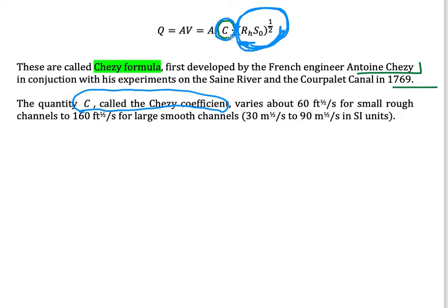So for our experiment, let's say we calculate this first. We assume that the value of C is equal to 1. Then we compare the value from this calculation with the experimental work. For sure it is not the same, because the value of C is not determined yet. So we could calculate the value of C by comparing with the real velocity or flow rate. I hope you could understand this, because I think it was already explained in fluid mechanics 1 previously.